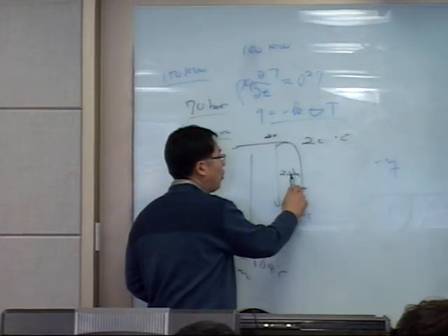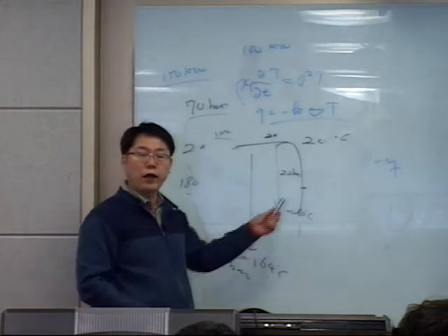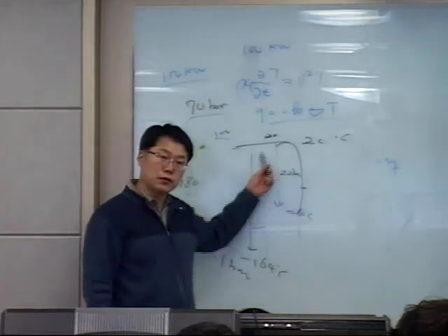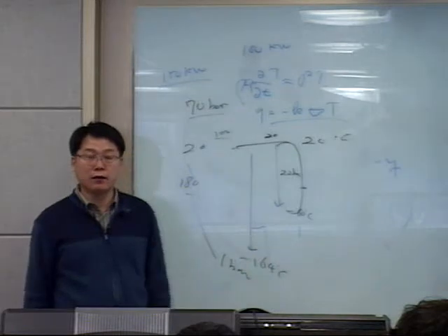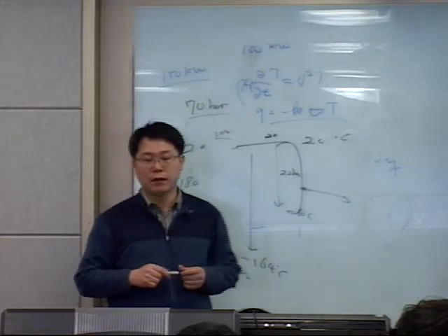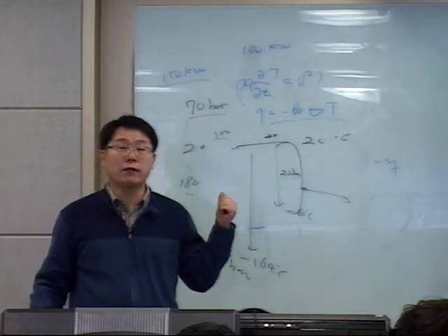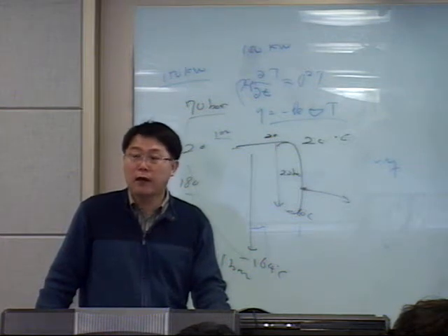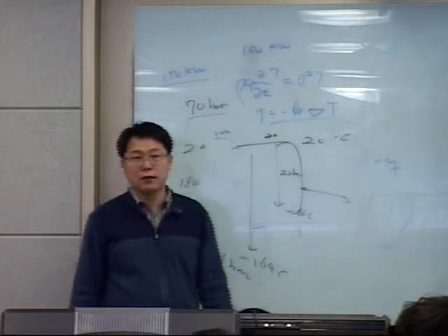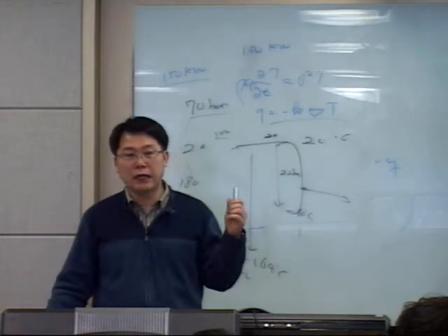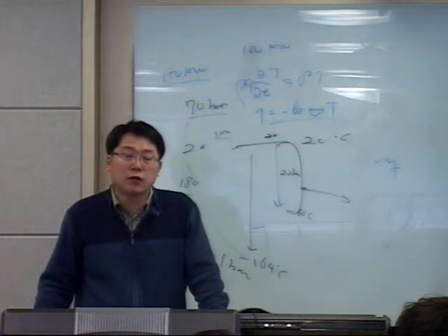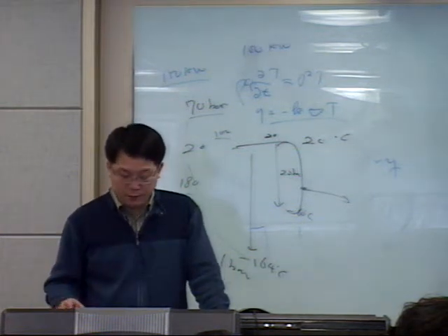If a small hole here, we have a large driving force, 20 bar, and a huge source here, a big tank. Then we have a dangerous LNG jet from the tank. If we have this kind of leak, it may easily destruct the ship. So another is the safety. Okay?